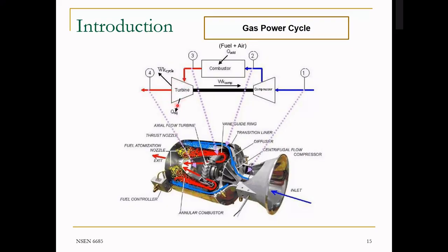For those coming from a non-nuclear, mechanical or engineering degree, very simple. Again, the major component is a turbine. And instead of supplying steam with some energy, we are supplying gas. Could be xenon, could be air, could be whatever it is. So it's a gas that goes through a combustor, which is a replacing component for the boiler or the steam generator, right? In the boiler, the steam generator will convert water into steam. In the combustor, we are heating up gas. So we supply cold gas, and it gets heated by burning fuel inside.